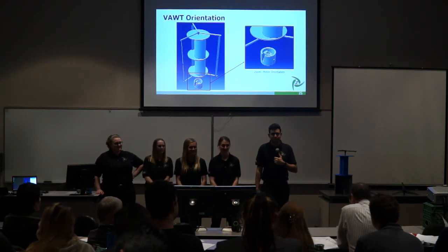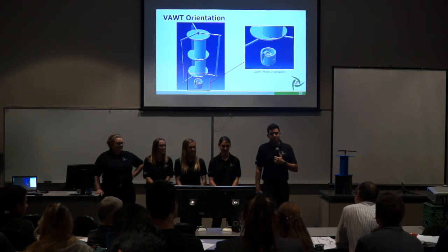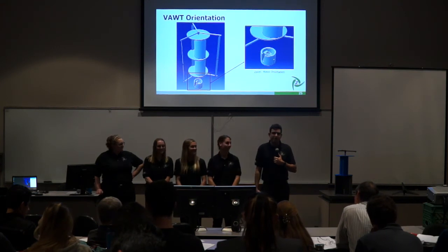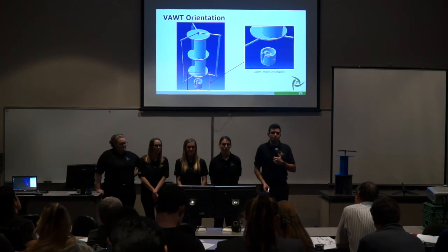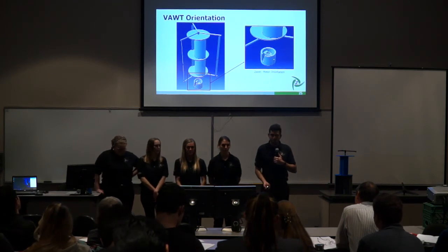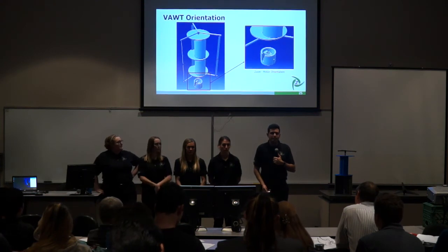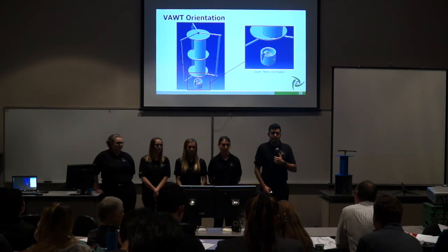The stepper motor, how did you discover that the stepper motor would work better than a DC motor or generator? This was based off of more research into similar projects. There are people who have made small-scale wind turbines just with a stepper motor. Most people do not use DC motors, as Tia mentioned. They have losses due to brushes, and stepper motors are more efficient at the lower speeds that we plan on spinning.